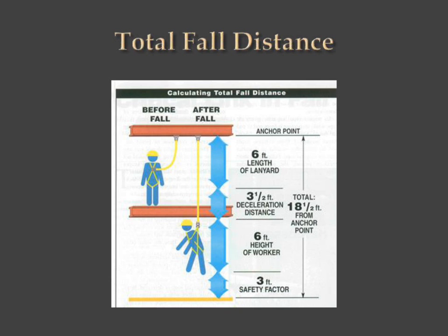Or you may swing into or hit something else on the way down if you haven't taken into consideration where you're going to fall. Let me give you a third scenario. What's below you, and if you're not hooked in one spot, but you're going to move with this system, does the floor or what's parked under it or placed under it change the dimensions that you're going to fall onto? For instance, if you've got a stack of boxes somewhere underneath you that you have to walk over that are only 10 feet below you, you know you're in trouble. So you need to take into consideration while you plan.